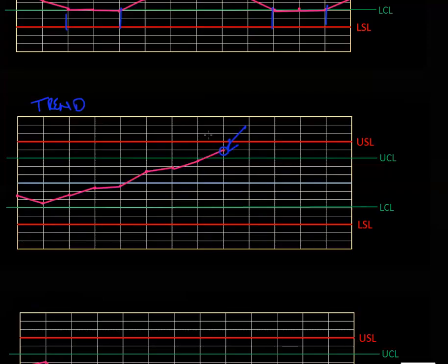Thinking back to injection molding or plastics extrusion, you have material passing over that die over and over again, and the die wears as the plastic keeps pushing past, so maybe we're measuring the outside diameter with this chart, and it's going to get bigger and bigger as the tool wears, and then eventually it goes out of control. So tool wear, machine wear, that type of stuff, if this is an X bar chart, and some source of variation, vibration or a misalignment of some sort if this is a range chart.